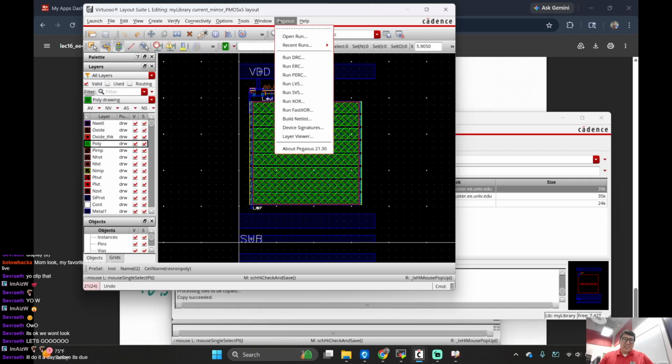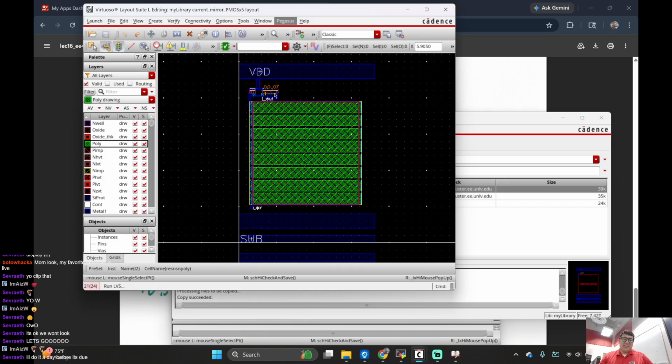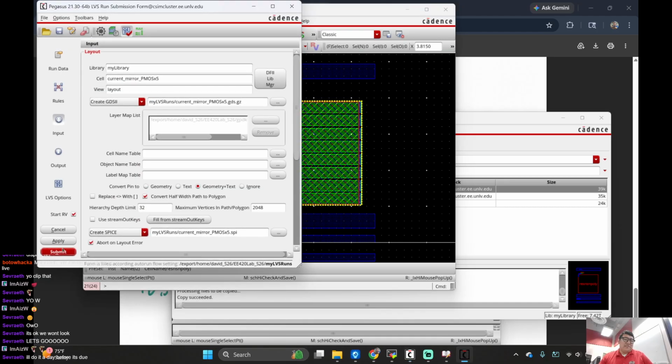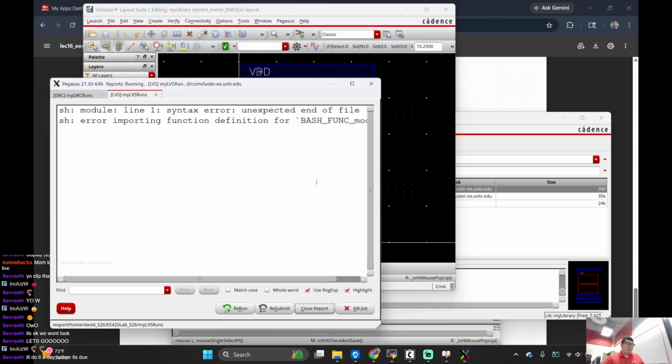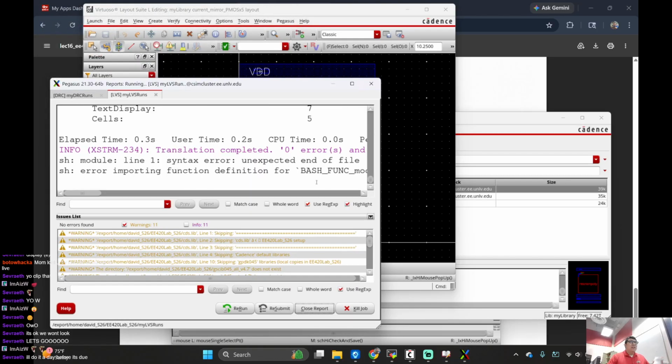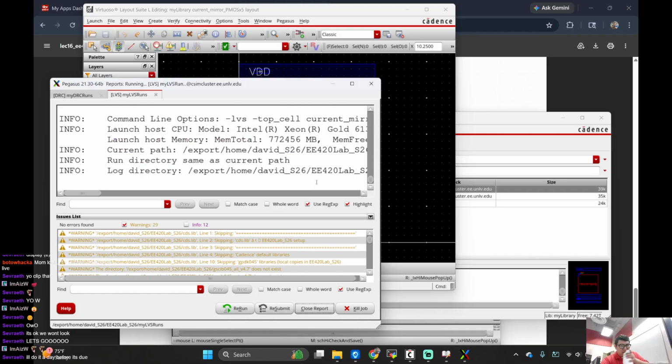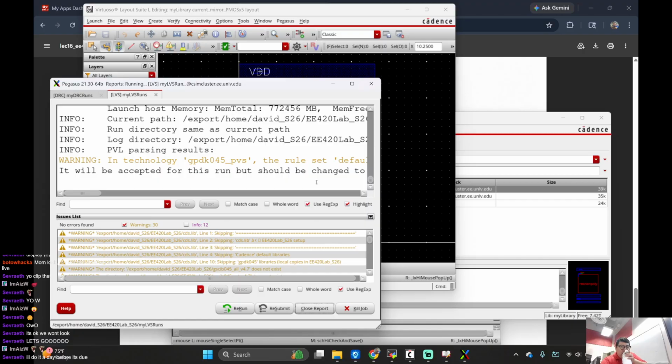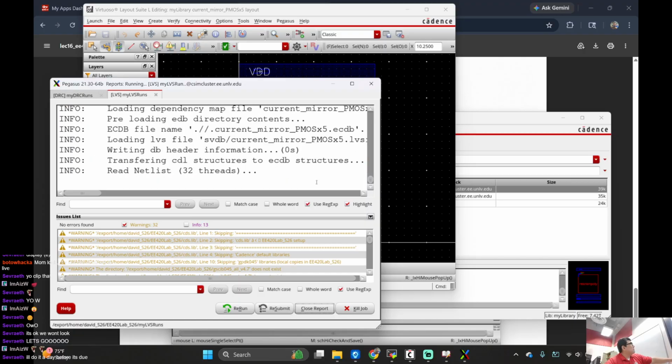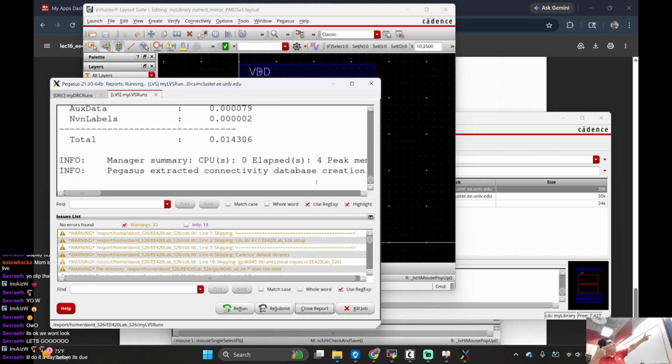Okay. Nothing's changed. Let's LVS it, because there's no reason to DRC it. DRC is for painting things. LVS is to make sure the netlists work. Come on, baby. Boom.